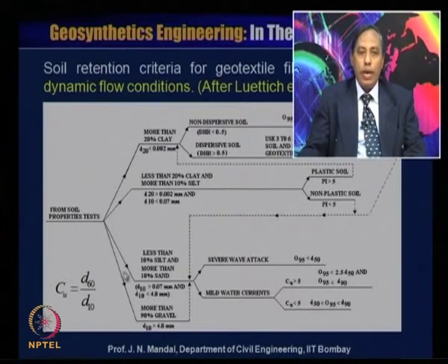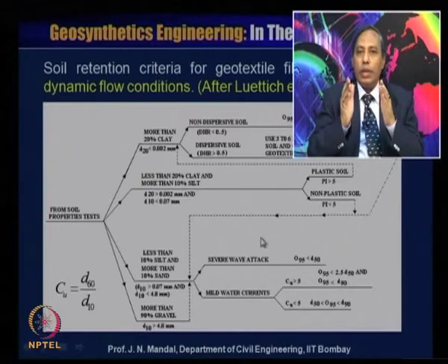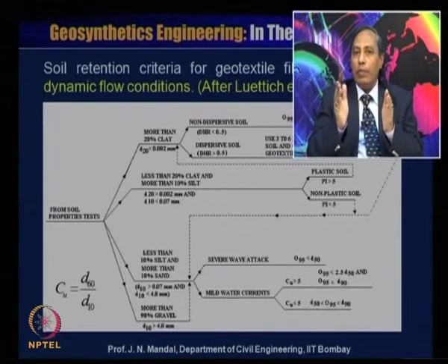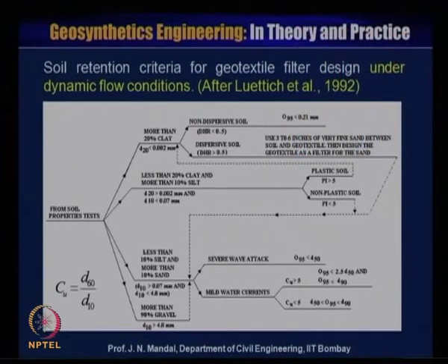And as you know, you can calculate Cu as D60 by D10. So for the soil retention criteria or geotextile filter design under dynamic flow condition, this is given after research, Giroud 1992. He has given two charts, one for the steady state flow condition, another for the dynamic flow condition.